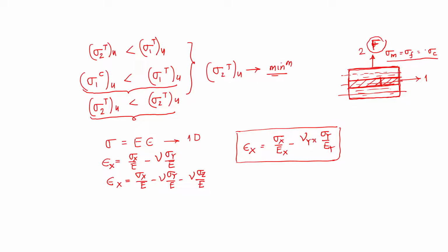But in this case, the fibers and the matrix in the representative volume element are equally spaced, and the fibers are throughout the length. The matrix length and fiber length are exactly the same. Therefore, the stress is the same, isn't it? But the strains will be different. The total elongation in this direction will be due to the fiber plus due to the matrix.